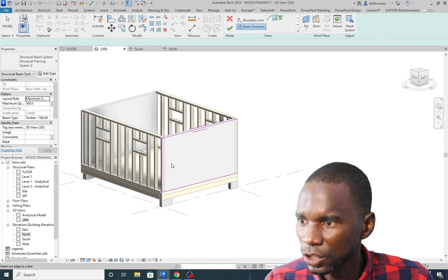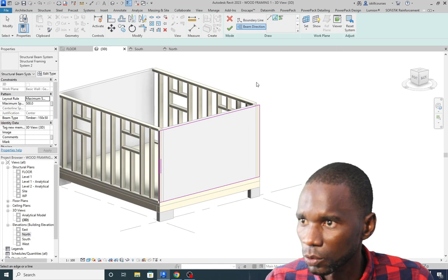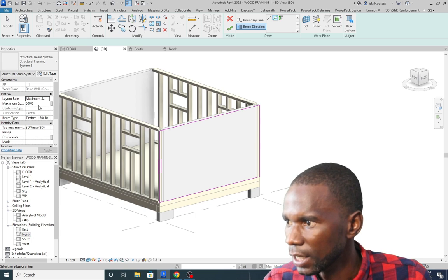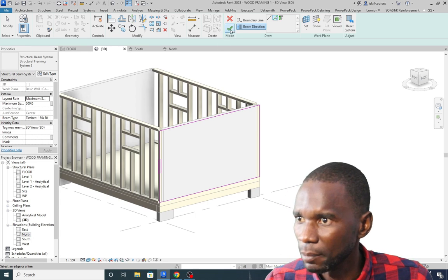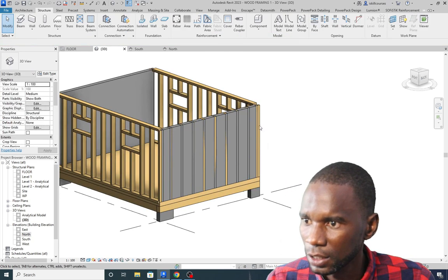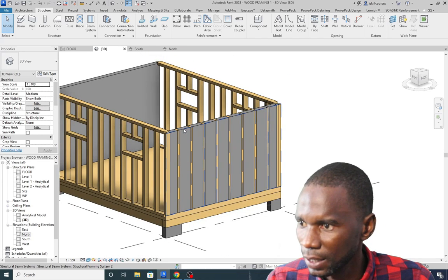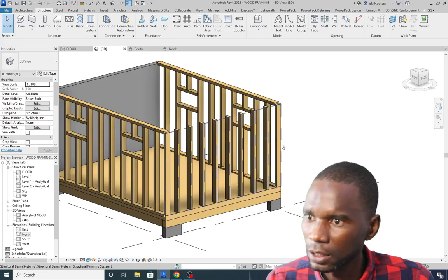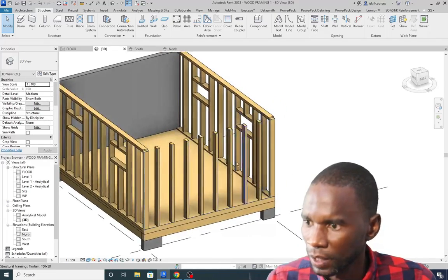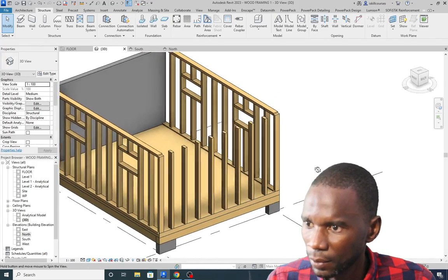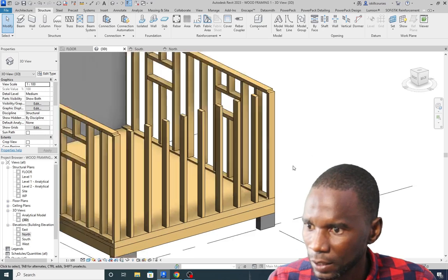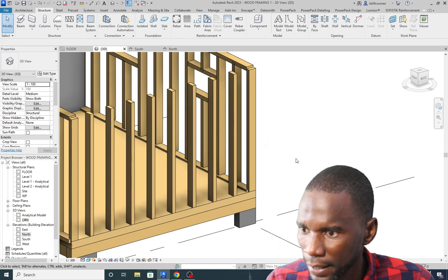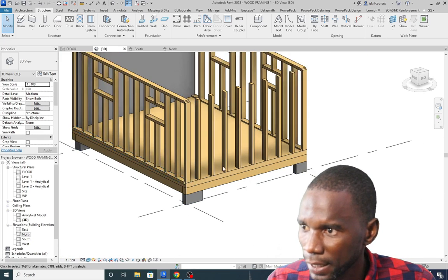And the beam direction, I just want to show that one in that direction, the spacing 500, and that is the member. Then I'll click on finish, click outside. Okay, now this time let me simply even delete the wall there because I've used it. I have my beams there. Then I just need the member there, and down there, these are the only members that I need. Also, I need to copy a member at the end there and one member at the end there.